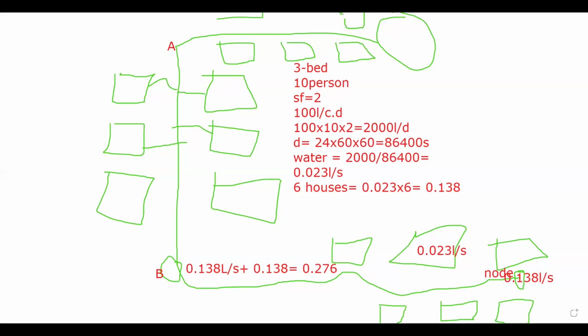Remember, these are uniform, 3-bedroom bungalows. It could be more than that. It could be upstairs. It could be duplexes. Once it's duplexes, all you need to change is the population equivalent. And we'll still come to that. Or what is the land use? If you design a virgin place and you want to design the water recirculation system, there are no houses, right? The first question you ask is, what kind of houses are they going to have there? Are they duplexes? How many floors? That one is for pressure analysis. But for the population equivalent, what is the population you expect?